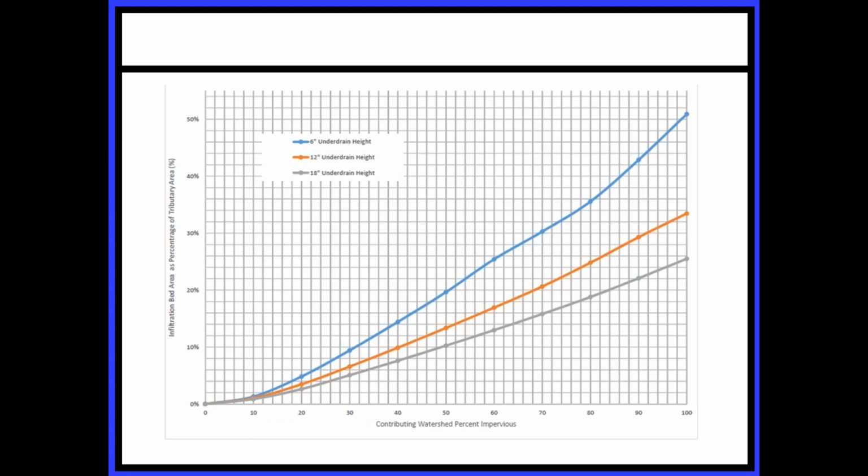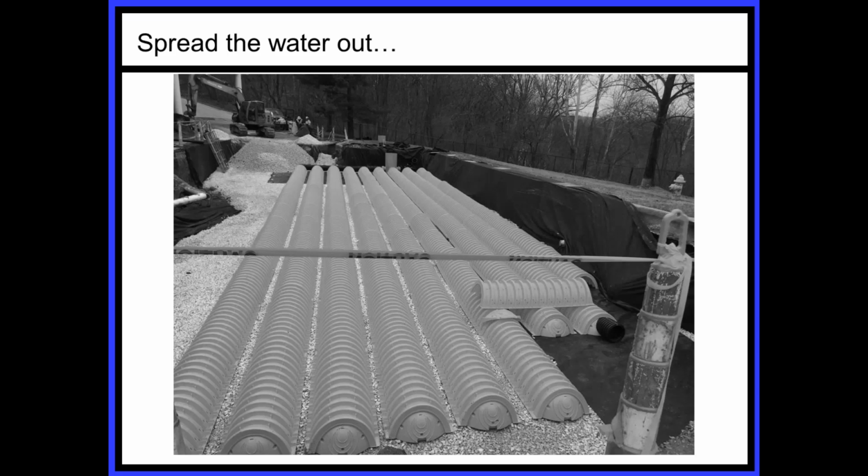Any deeper than that you're really not seeing the value. So what we recommend is that you look at an infiltration depth of about 18 inches or less. But you could go deeper. It's just you're storing water for a longer period of time and you may not see the end result. Again, the whole idea is to spread it out. So when you look at infiltration, it's less about a volume than it is about the area you're infiltrating. So oftentimes the idea is to use a smaller chamber like that's used often in septic and use more of them, so you spread the water out over a larger area and it gives more infiltration surface.